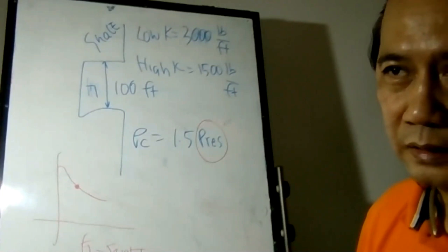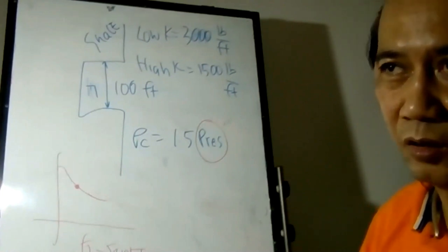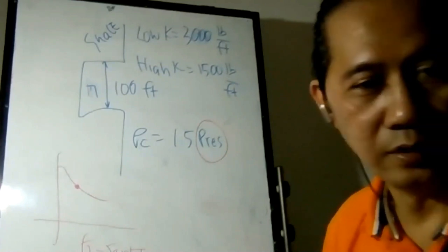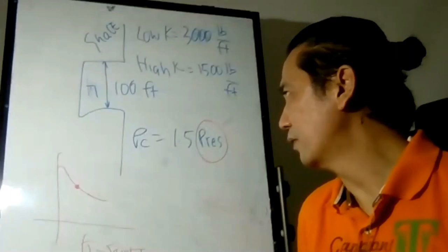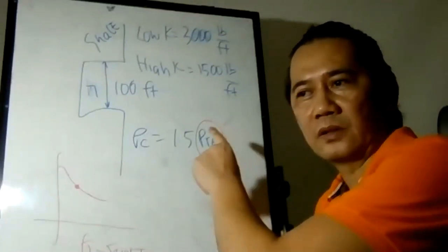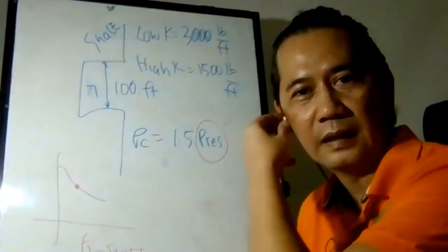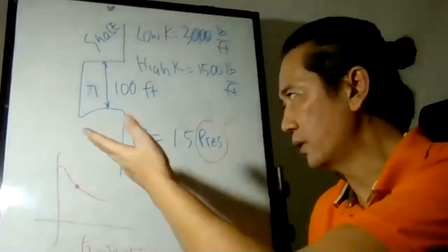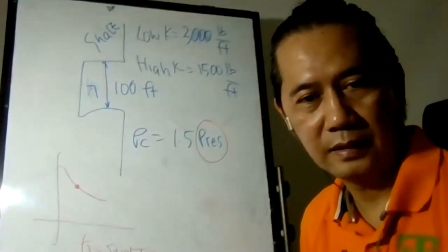But if you ask me, can I get the direct closure pressure by having a longer leak-off test? No, you don't. Right? So no, you don't. By having a longer leak-off test, you will get a better reservoir pressure, because then you will have a higher chance to reach your radial flow when compared with a very short leak-off test or decline, right?